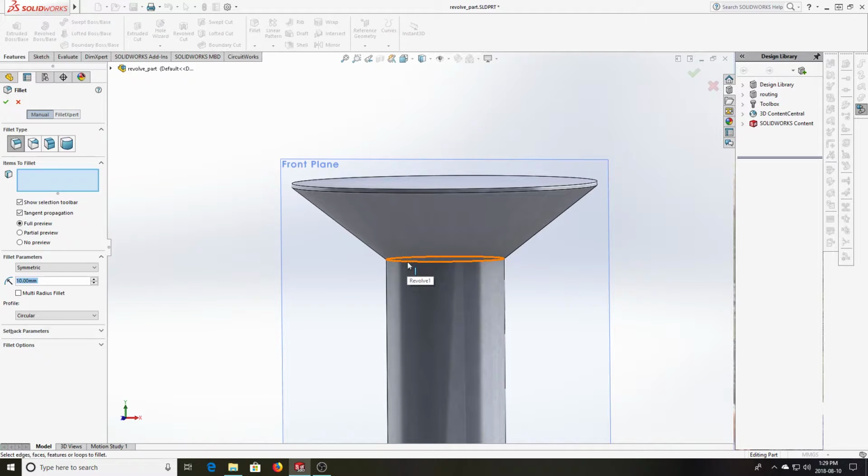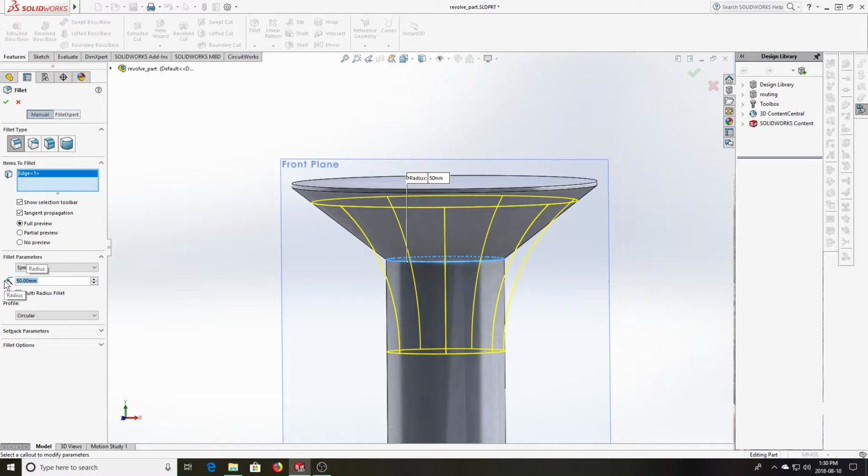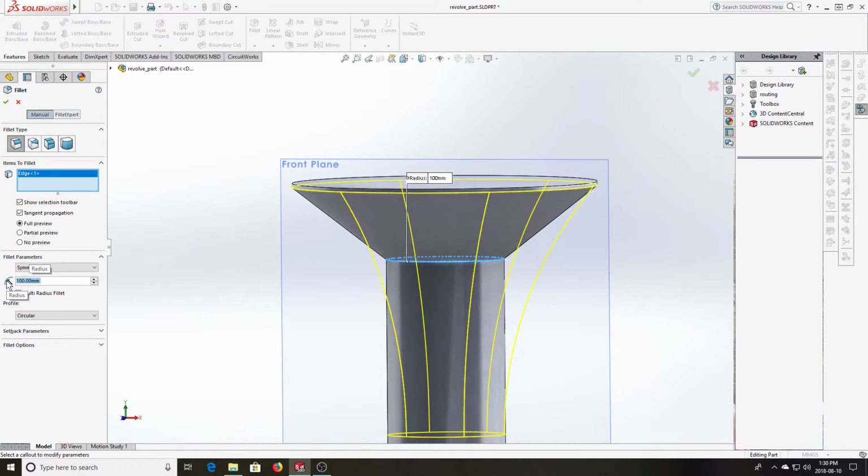I'm going to select this. I just click the fillet tool in Solid, and the filleting edge shows me how it might round that in the middle. I can change that dimension for the fillet. I can make it 0.1 millimeters, in which case the fillet is tiny. I can make it 50 millimeters, in which case it would be quite big. If I try to make it even bigger than that, it will still try to fillet it, in most cases.